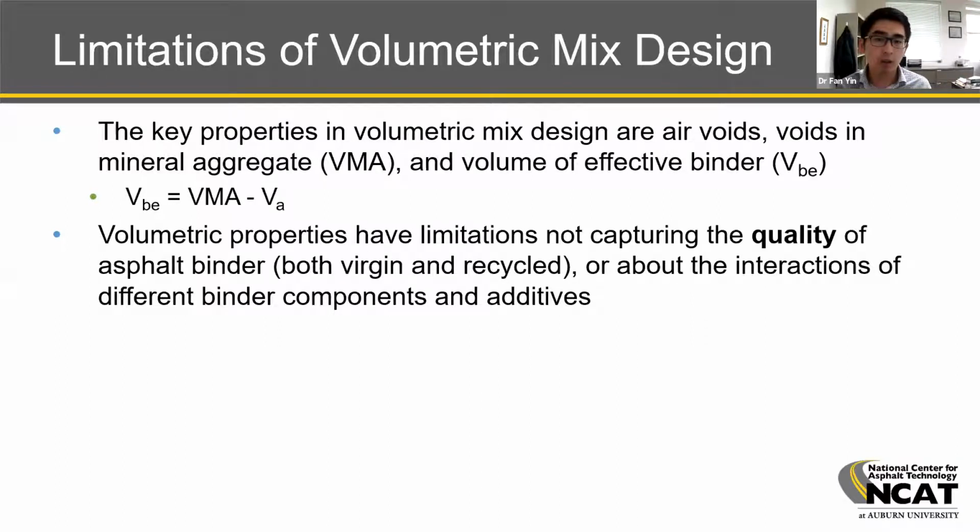That works to a degree, but if we have recycled material in the mix, or we start adding asphalt additives into our asphalt mixture, then just looking at the VBE or other volumetric parameters will not be able to capture the quality of the blended binder or the interactions between the different binder components and additives. That's one of the main limitations of the volumetric mix design.